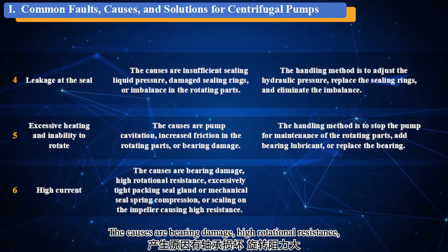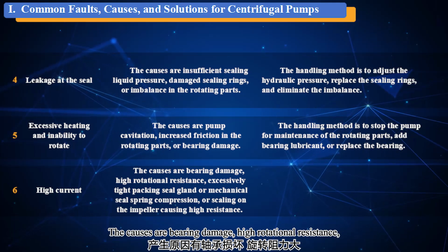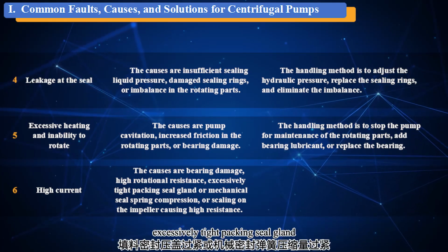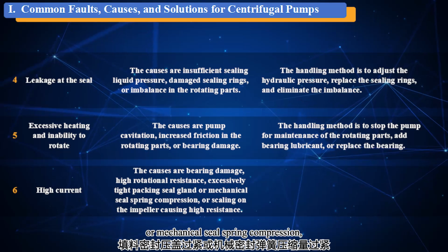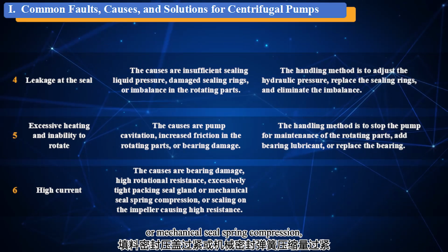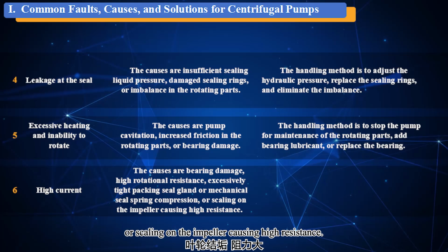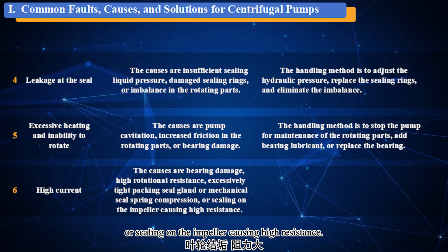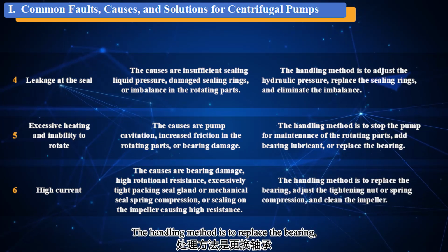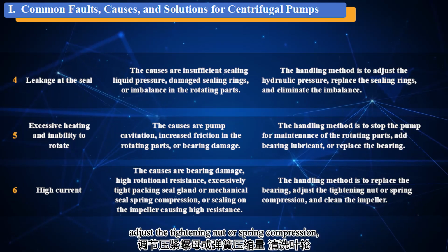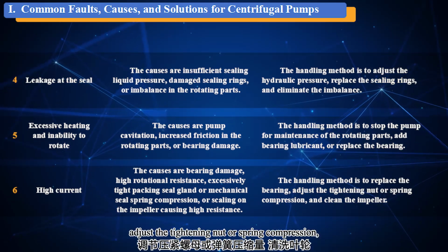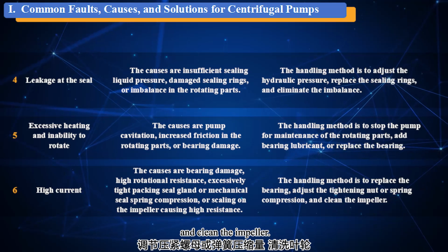The causes are bearing damage, high rotational resistance, excessively tight packing seal gland or mechanical seal spring compression, or scaling on the impeller, causing high resistance. The handling method is to replace the bearing, adjust the tightening nut or spring compression, and clean the impeller.